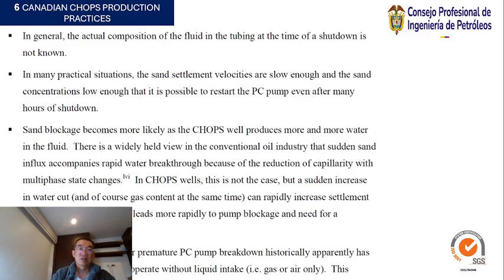In many practical situations, the sand settlement velocities are slow enough and the sand concentrations low enough that it is possible to restart the PC pump even after many hours of shutdown. Sand blockage becomes more likely as the well produces more and more water in the fluid.